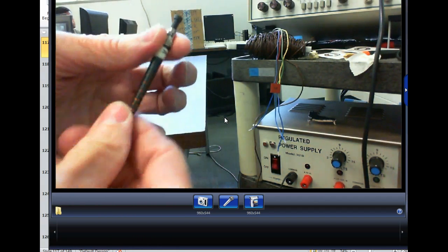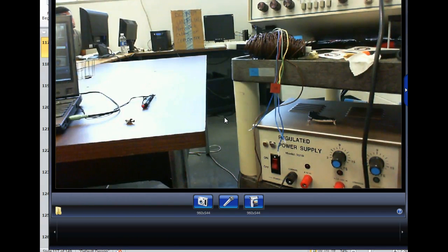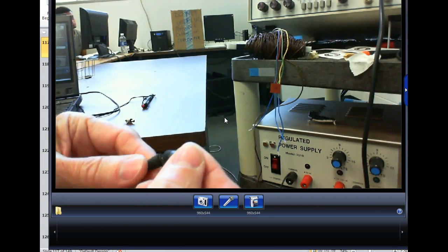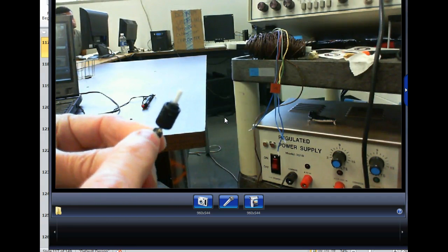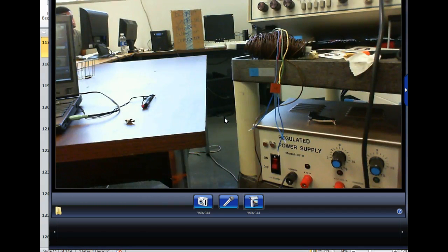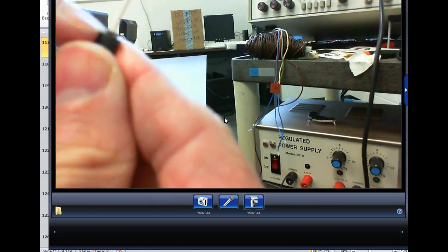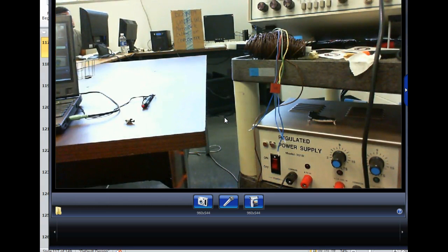These are cute little boots. And here is the actual back shell. I'll take the back shell off. The back shell is where we actually crimp. Can y'all see that? What we want to do is crimp this onto the Kevlar, right? And also the inside jacket. We'll look at that in a minute.